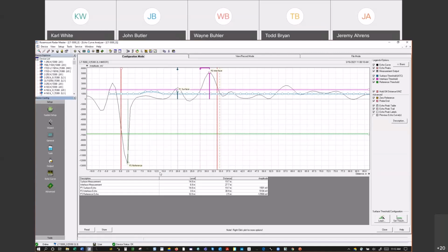But it's super hard to make that claim on an empty tank. On an empty tank, you're probably going to go back when it gets product in it to finish setting it up, to dial in your top level exactly right with a hand gauge and all of that. So it's empty tanks. Gauges don't like empty. They like to read a level. And if there is no level, they kind of generate noise.